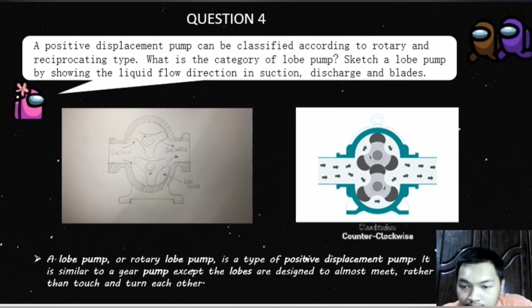The synchronous rotation of the rotor pair and the decreasing pressure chamber create an overpressure on the discharge side of the pump. The flow direction can easily be reversed by changing the direction of rotation.